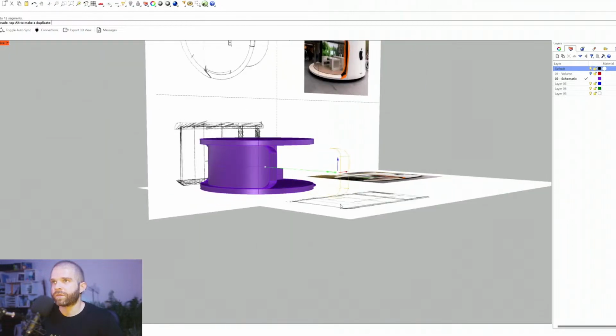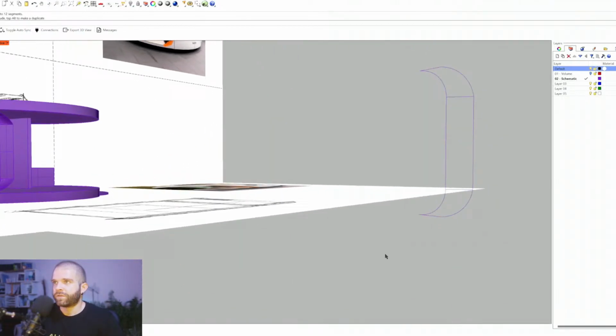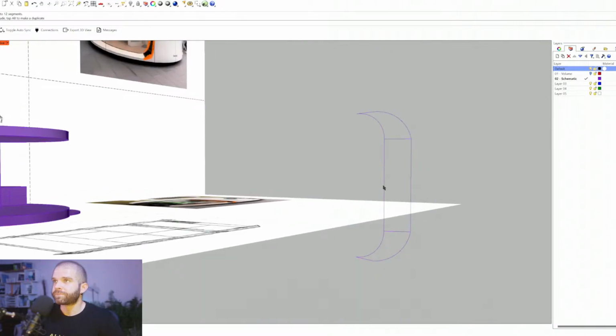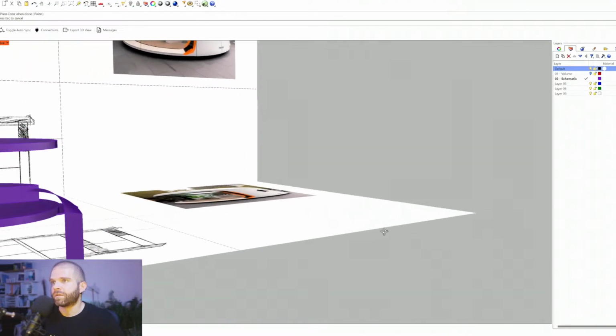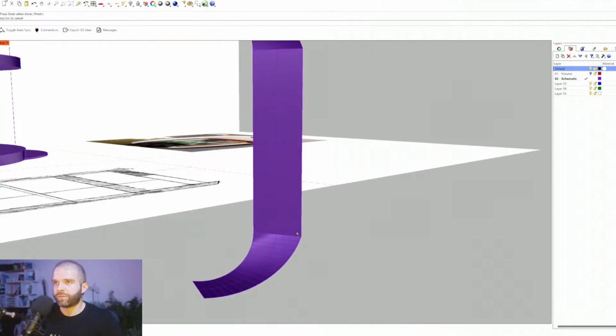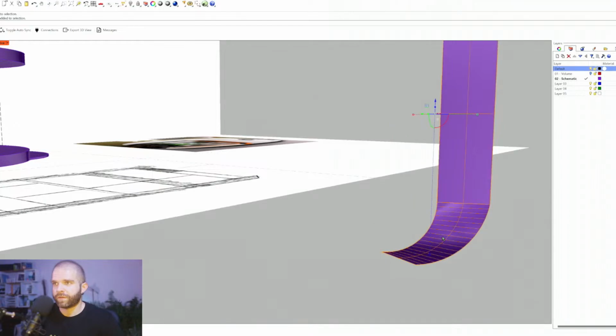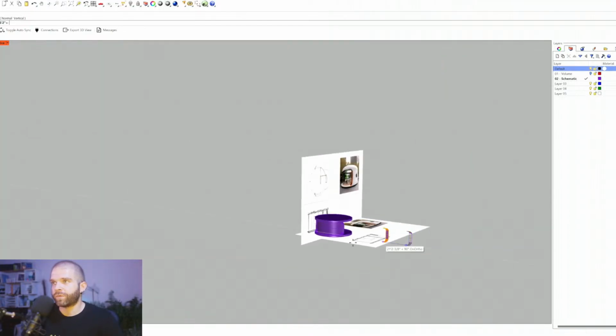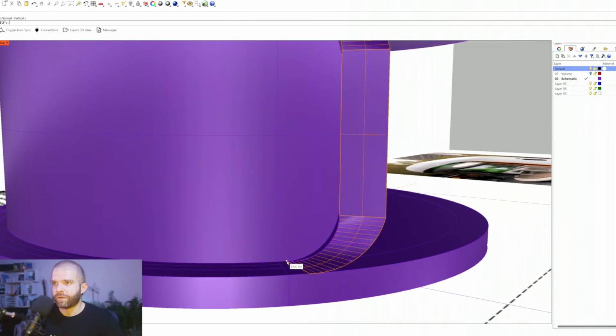Let me just separate this so we can see. So it's isolated over here. Okay, so now I'll join these three. Join and join. And let's try lofting in between. Okay, so much cleaner. So basically what we did there was just isolated both edges and then built a surface in between them. And that surface that got built in between is much cleaner. So we'll have that replace that existing screwed up surface. There you can see the difference, right?